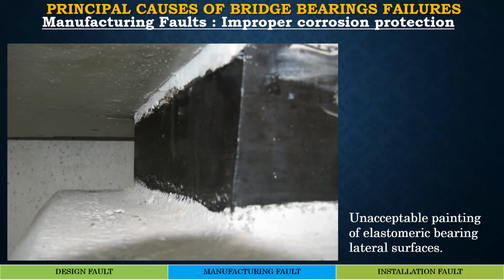Sometimes painting cover is used as a mask hiding cracks on elastomer surface, and that should be prohibited. So one must be aware that when it comes to elastomeric bearing, no painting should be done on top of that, even to hide anything, and that is completely strict no.